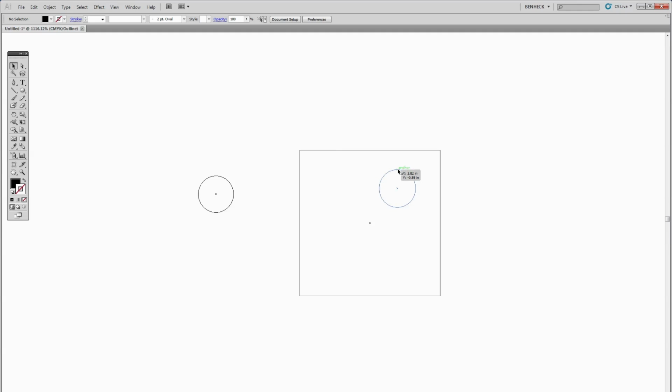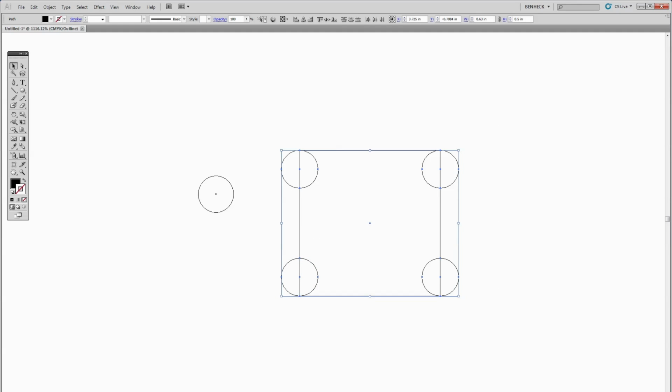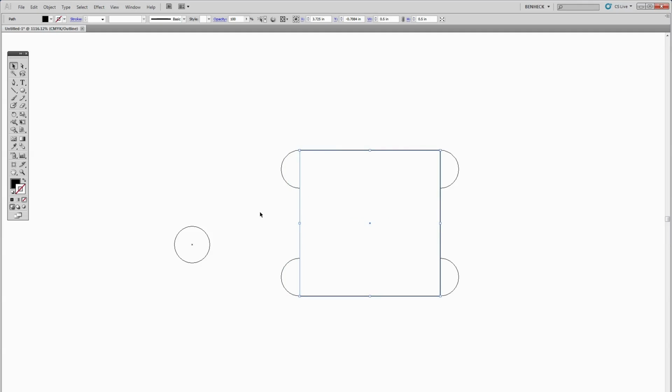Firehouse? So what I like to do is make slotted tabs. I'm going to make a circle that is slightly larger than my bit, so 0.13 inches. I'm going to put this in all 4 corners, and now I'll combine it. So now when this cuts out, the bit will go along on the inside, and it will leave a clean space for your square tab that you put into it. And you can actually make it a little bit more aggressive than that even.